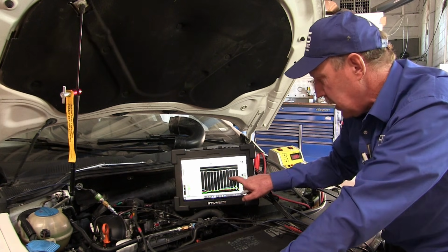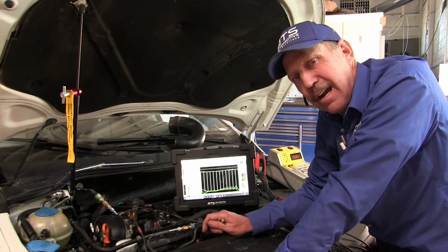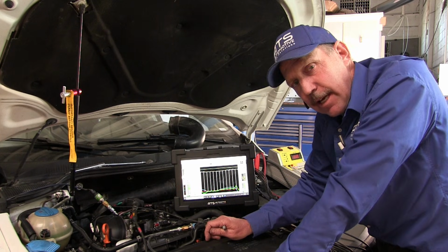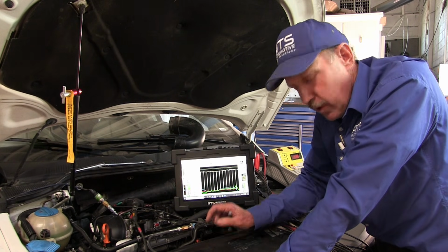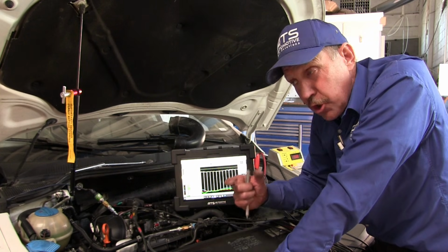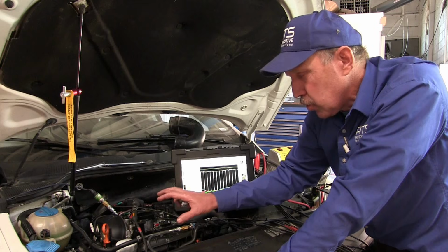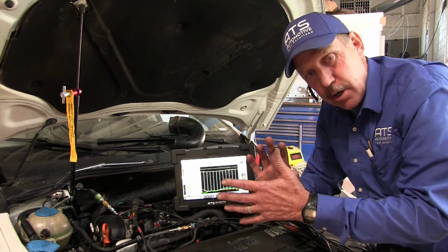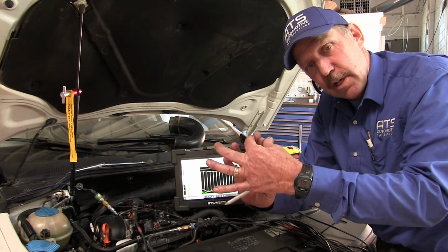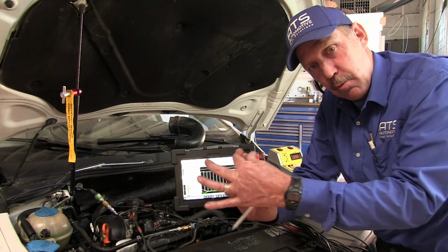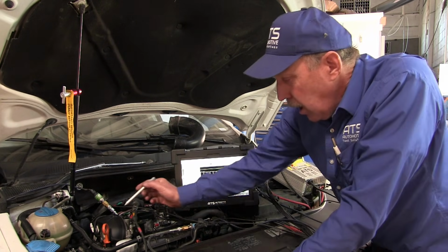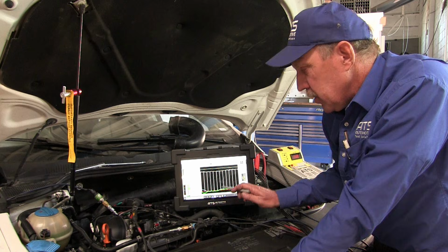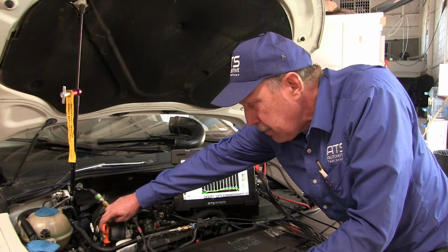So this is saying that the phaser is not in operation. I'm okay with that. But these phasers on the intakes, they can break. And when they break, there's a little valve. These are spool valve assemblies that control oil to a vane motor. These are vane motors, and if I put pressure on one side or another, I can drive the cam one way or another. Now, since the intake cam is off, and since this isn't pulsing, I'm thinking that this is my problem here.